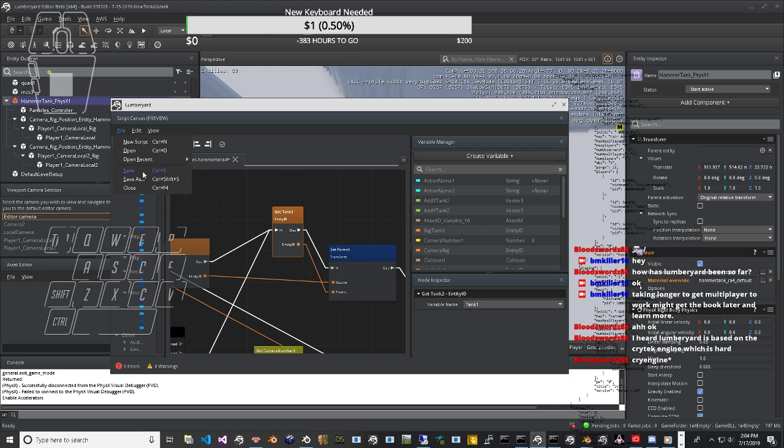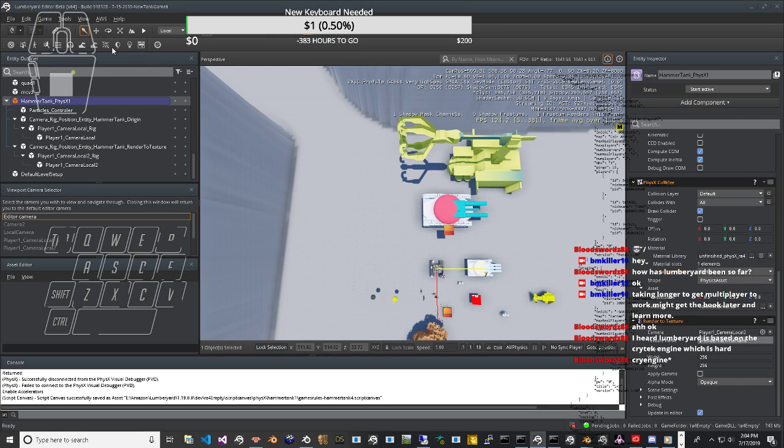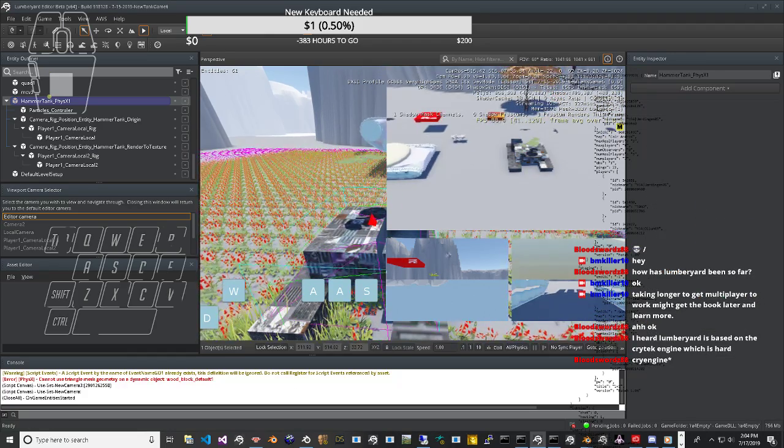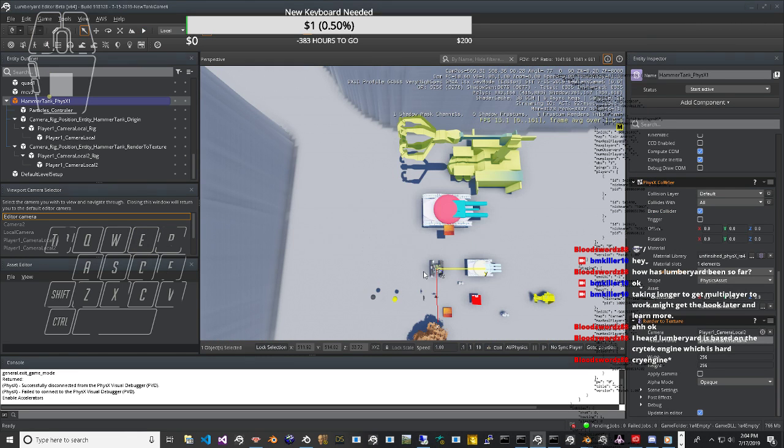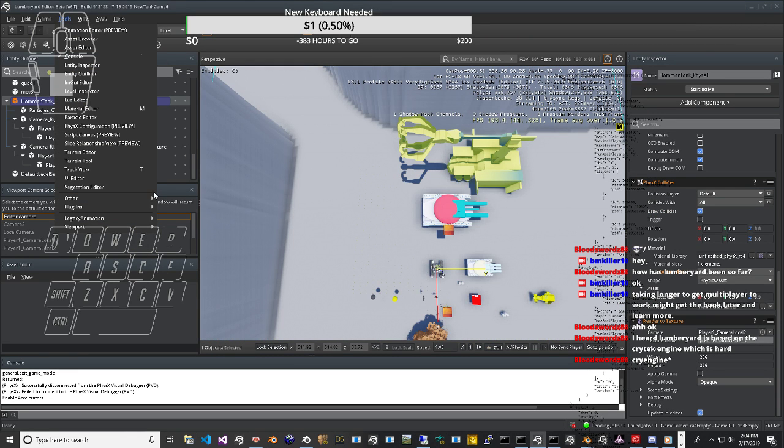To understand the magic formula, we need first to define its inputs, which include slip. Slip is an indirect measure of the fraction of the contact patch that is sticking. It is frequently asserted in the literature that a tire with no slip at all cannot create forces. It has taken me a very long time to accept this assertion. Why can't I steer a tin toy car with metal tires on a hard surface like Formica? If there is any slip in such tires, it is microscopic, yet there are sufficient forces to brake and steer, even if just a little.